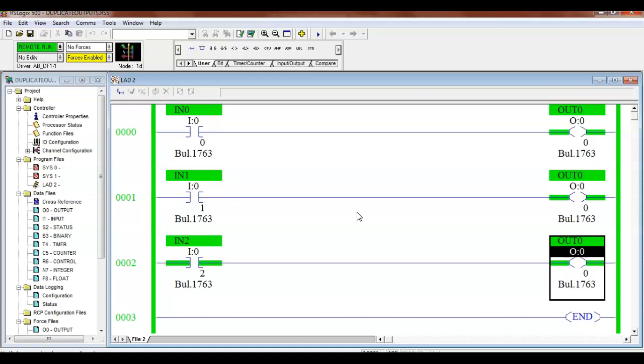So these up here make no difference. So the whole thing is controlled by whichever one is in the last rung. The furthest one down controls that output. The other one made no difference. So I've wasted all this time, and you understand that. So this is why we can't duplicate outputs. The way the PLC scans this program, it scans this line, scans this line, scans this line. This was the last one scanned. So when it updates the output, which one does it pick up? It picks up the one that's got the biggest rung, the largest rung number.